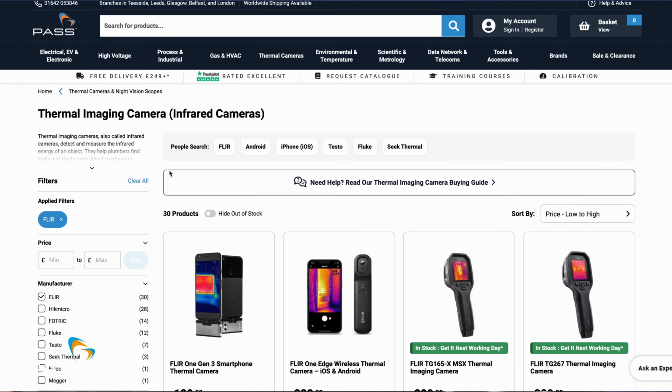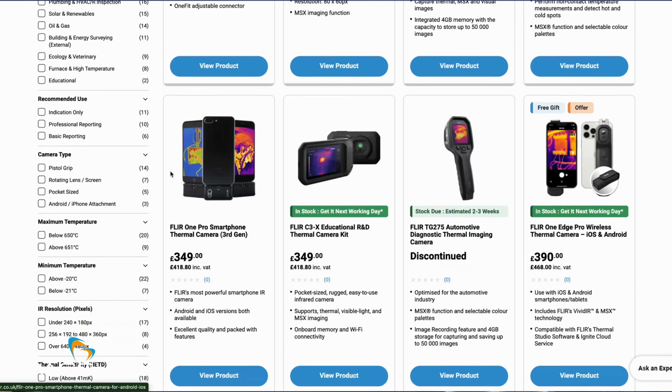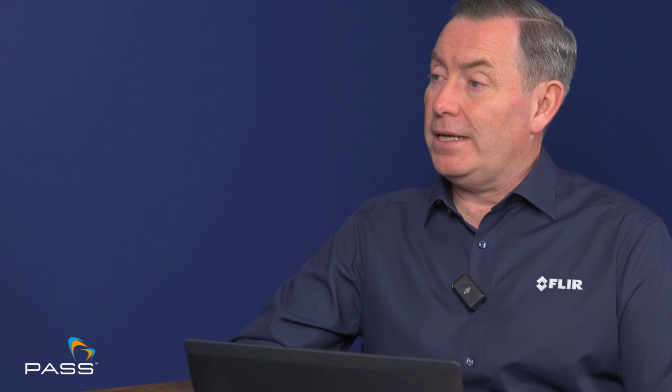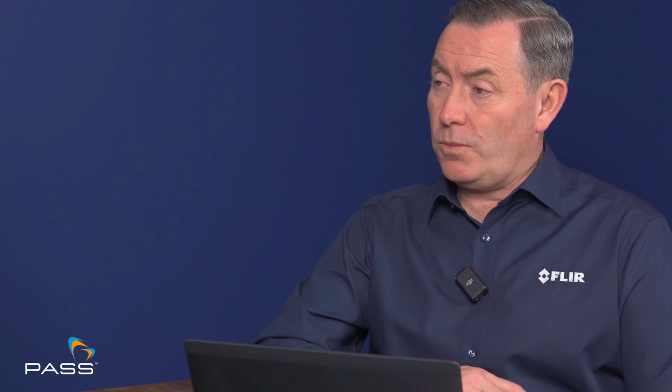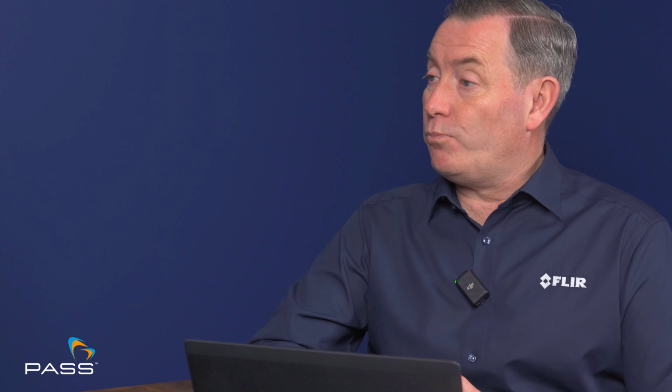So would that be the E series? The T series? This could be the CX, it could be the EX, it could be EXX, it could be T series. Ultimately, these cameras produce a radiometric JPEG image. Radiometric means that there's temperature data, thermal data included in the image. And then you need the software to be able to analyze the image. Otherwise, you would be able to open the image up just with a normal Windows tool, but it will only be an image to look at. You won't be able to actually do any analysis. So you do need the software for that.